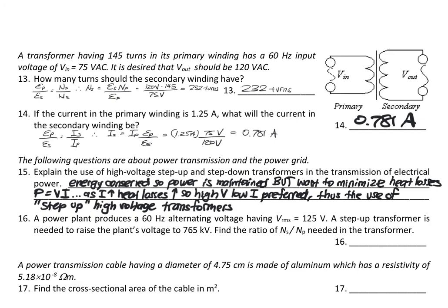And the reason for the explosions, like for instance for transformers, those are the cylindrical cans you see up at the top of power lines. Those are transformers. Usually, if they're transformers near your house, those are step down transformers from the high voltage lines to the lower voltage lines that are going to your house. And if they explode, and sometimes they can explode even near your house, there are videos of that, it's because if there's a short circuit inside of the transformer, or if the insulation in the transformer fails, creating a short circuit, then you do have a spike in the current.